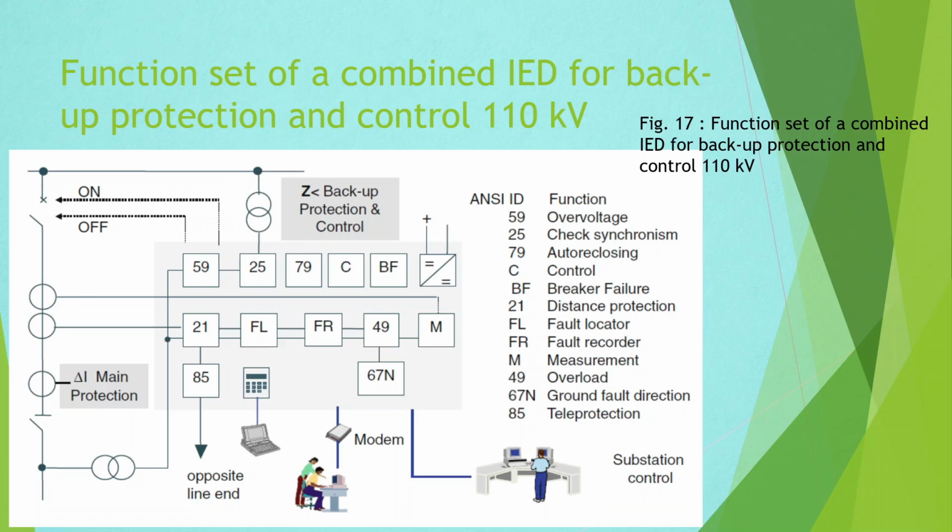As the name suggests, the overvoltage protection has the task of protecting electrical equipment against overvoltages. Overvoltages may occur on long, low-loaded transmission lines, generating an excess of reactive power. The overvoltages may cause, for example, insulation problems and damages.